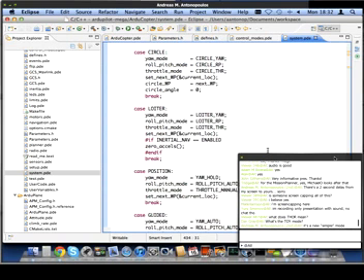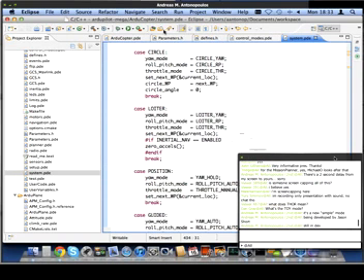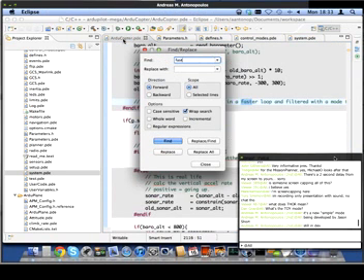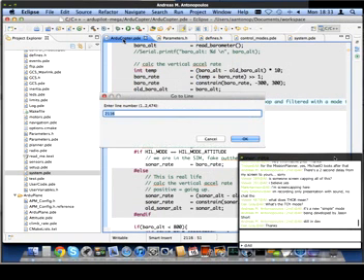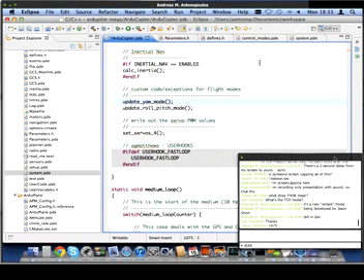Moving along, once we have these 3 variables set, the yaw mode, roll pitch mode, and throttle mode, how does that actually make a difference to the controllers that are being executed? If you go back into ArduCopter around line 1075, you'll find that in the fast loop, which is running at about 100 hertz, we call these 2 functions. You can go to ArduCopter.pde line 1075. Sorry, 1,000 what? 1075. Yeah, there we go.